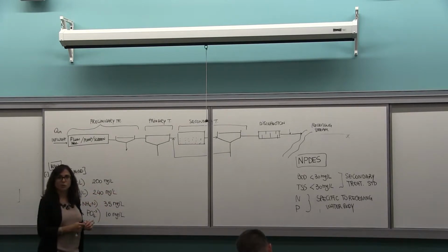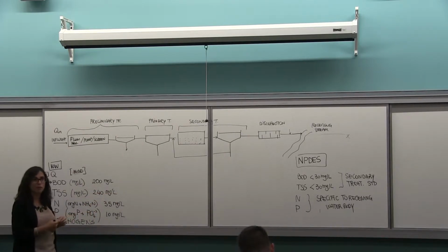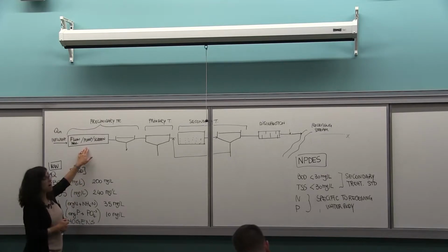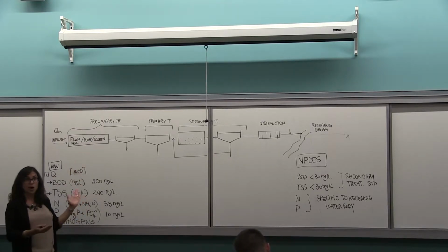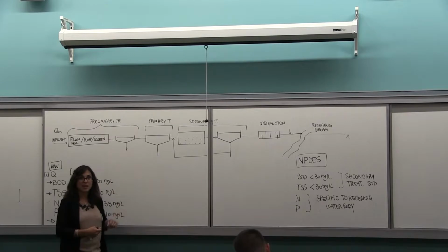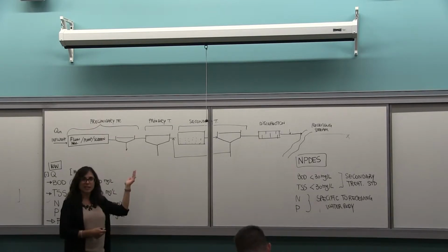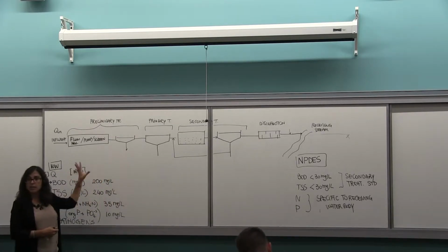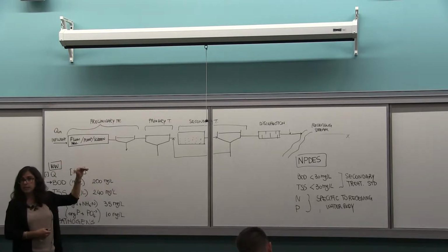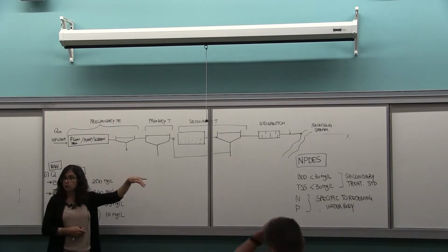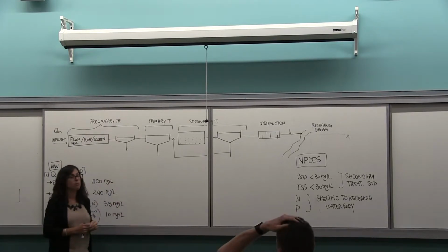Even your permit will give you the flow that you can treat. Pumps we usually need for all the process. It's a gravity flow, so we increase the head at the beginning of the plant so that it can then flow through gravity during the whole plant.